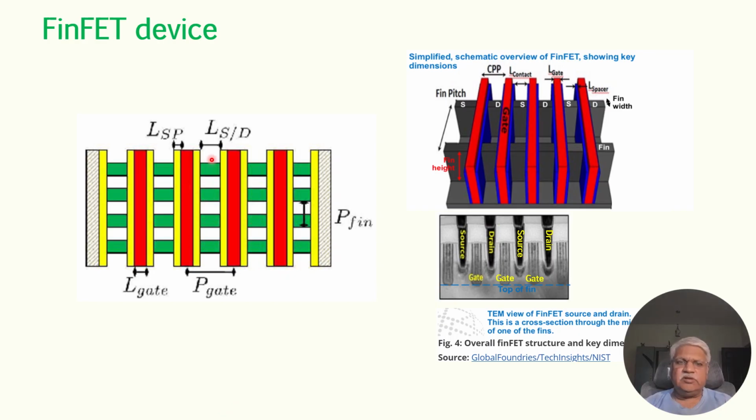So here is the layout view, and this is an equivalent representation of how it would be in silicon. This is the TEM view or scan SEM view in some cases, and this is one fin, another fin, and these are the fins we are talking about. For representation purposes, I am comparing this with the layout view. So this is the fin pitch.